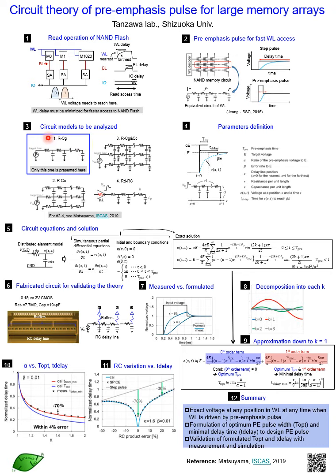So there are various word line circuit equivalent models. The simplest one is this RCG model, and G indicates grounded. Another model is RCCC, where C indicates coupling to the next neighbor word lines.